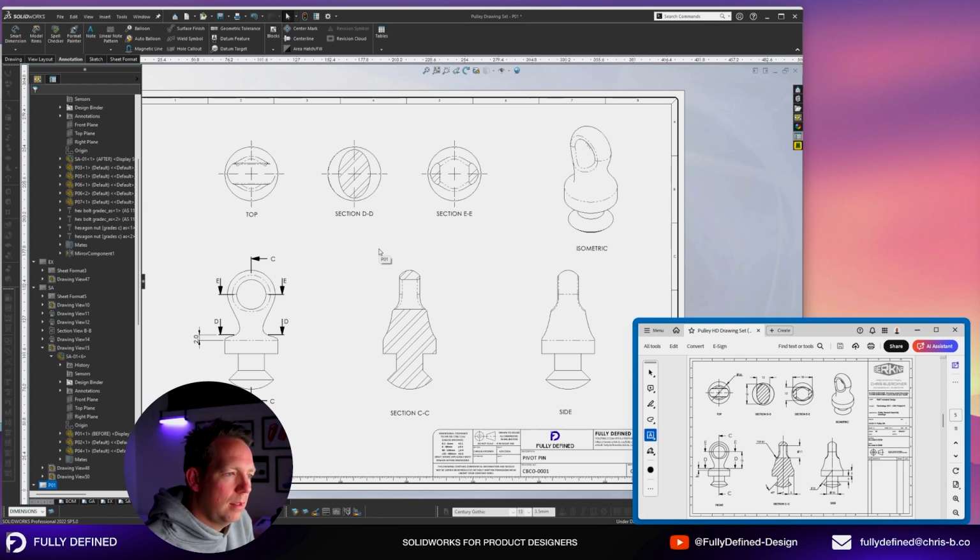Think carefully about what dimensions can actually be checked by the supplier. So if they're using a jig or a measuring tool, can they actually measure if that radius is 0.2 or 0.5 millimeters? Probably not. That's probably not something that you need to dimension on your drawings. This project and the example drawings you have will have a lot of dimensions that you generally wouldn't need if you're producing these parts, but it's part of a process of learning how to add dimensions to drawings. So that's why there are lots of dimensions in these drawings that you'll see.